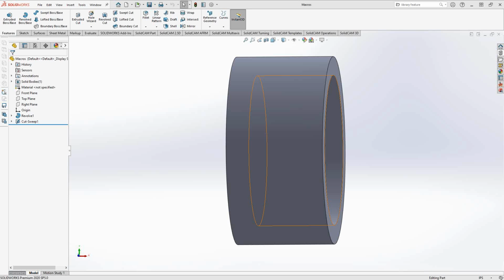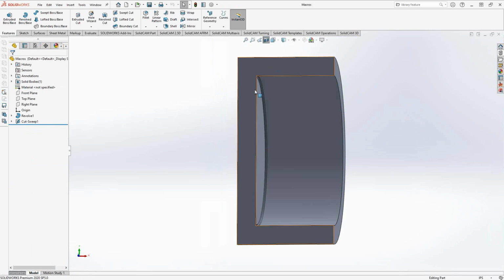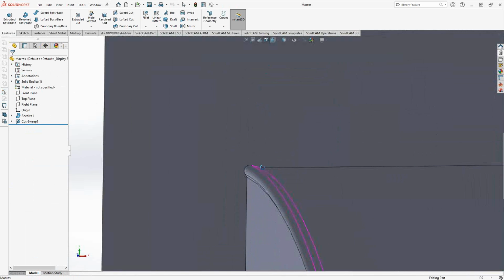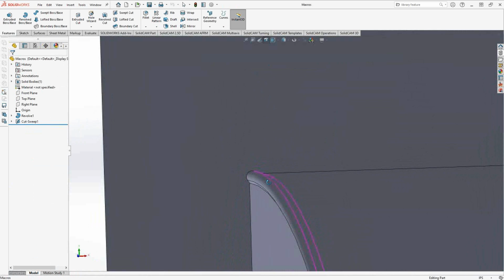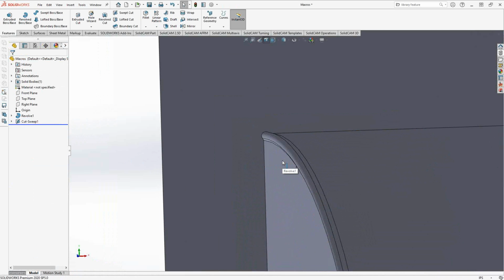And in this case, what we'll be talking about is an undercut in turning. So if we take a look at my part that I have on screen right now, and just get a cross section of that, there is kind of an undercut, kind of a relief that I've put on the back there, because in the original design, it would have been just a 90-degree corner. If I just bring this back, you can see that it would have been something like that. That's not machinable, so I'm actually just going to add that little bit of a relief there.